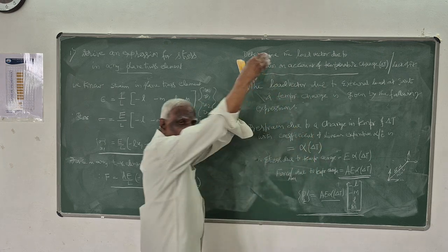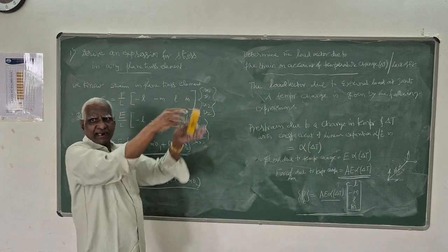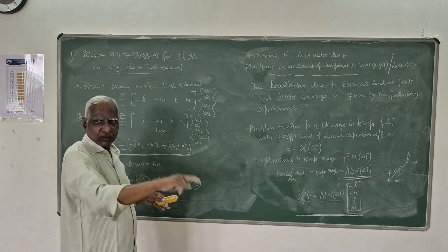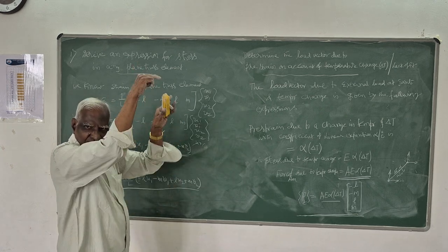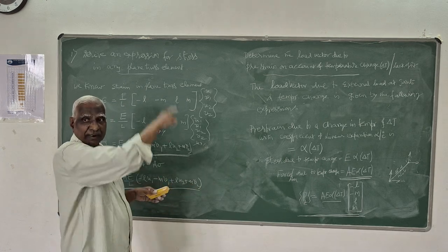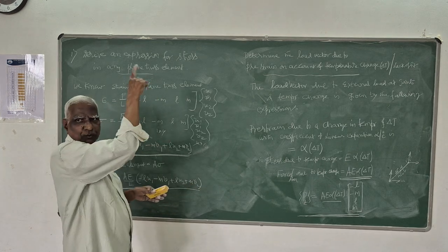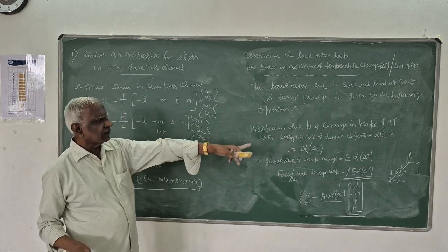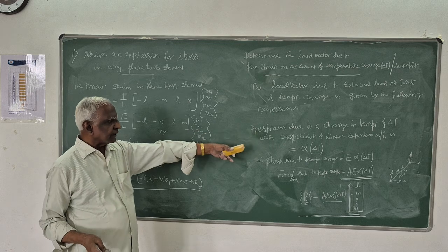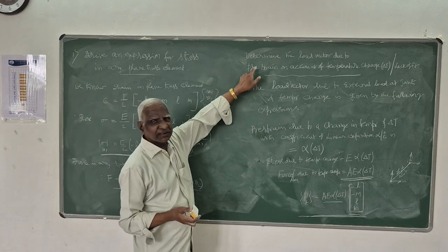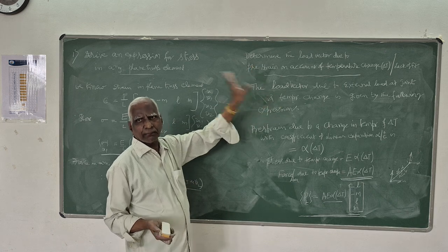Determination of load vector, the right hand side: u1 corresponding to the u1 direction, v1 direction, u2 direction, v2 direction. What is the load? P in the direction pu1, pv1, pu2, pv2. What are the loads? Due to temperature change as well as lack of fit. That is due to free strain, lack of fit or temperature change.